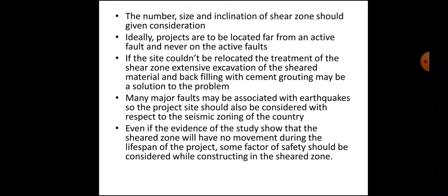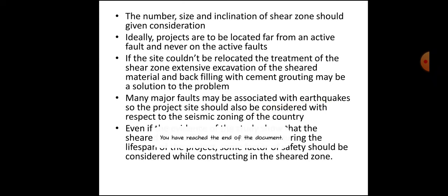Many major faults may be associated with earthquakes, so the project sites will also be considered with respect to the seismic zoning of the country. Even if the evidence of the study shows that the shear zone will have no movement during the lifespan of the project, some factor of safety should be considered while constructing in a shear zone.